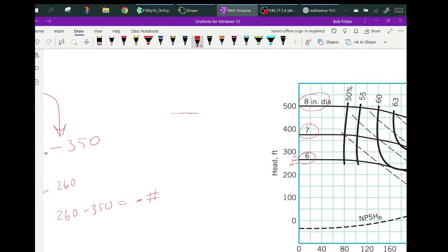So essentially a pipe could come in here, flow could come out here, and out the water would come this way. So it's the internal diameter of the rotor in there. It's not the diameter of the pipe. So the 6-inch diameter pump just simply doesn't have enough head to make it.